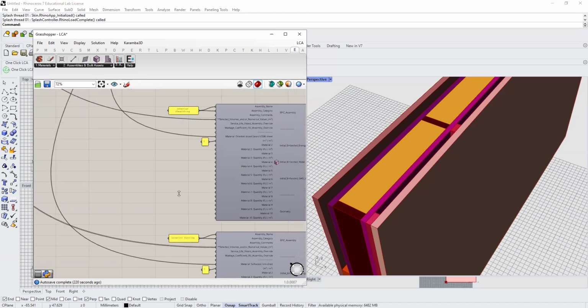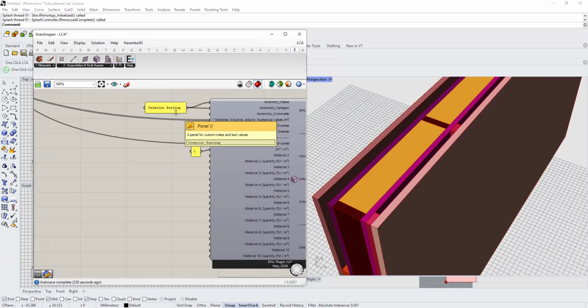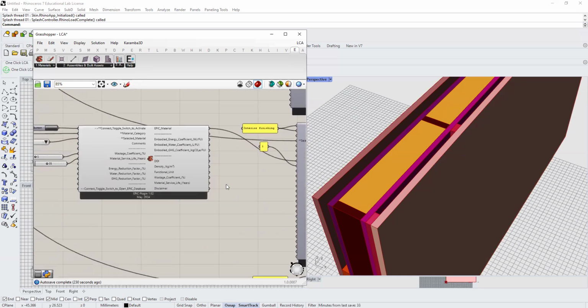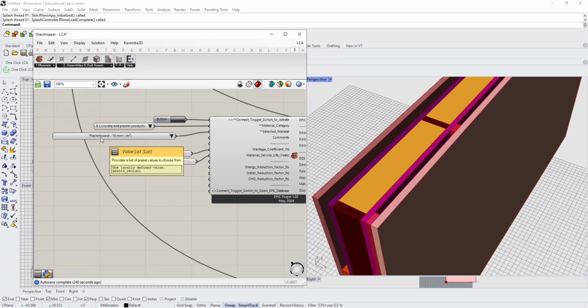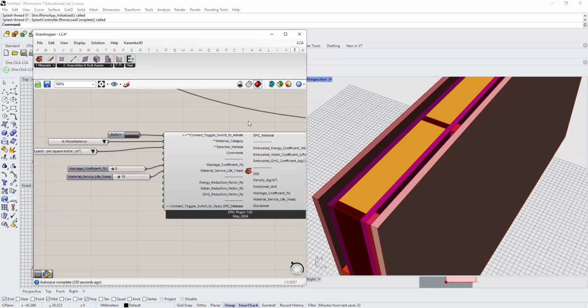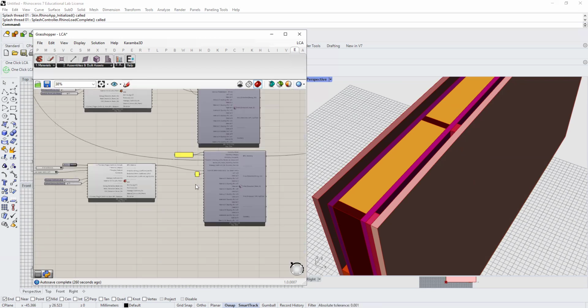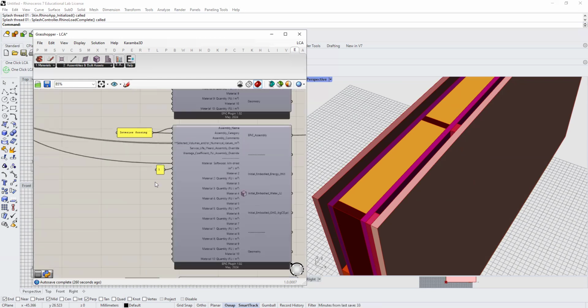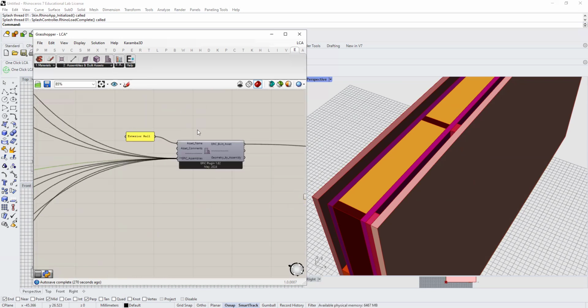Exterior sheathing, again, the same kind of material, but it is a different geometry. And also for interior fairing, I use the same material I defined above. And for interior finishing, I just chose a concrete or plastic products category and used a plasterboard of 10 millimeters. And finally, for interior paintings, I explored the miscellaneous list and chose water-based paint per square meter. So these are the different materials.